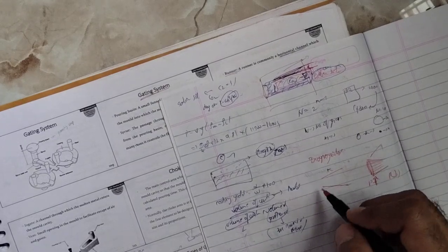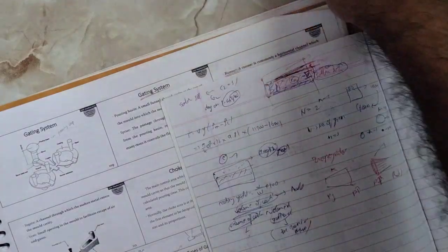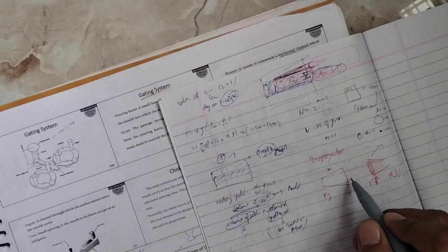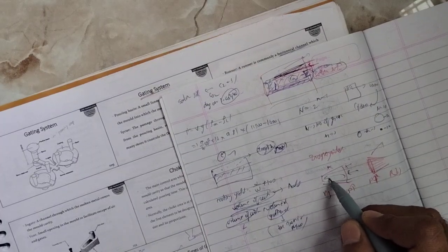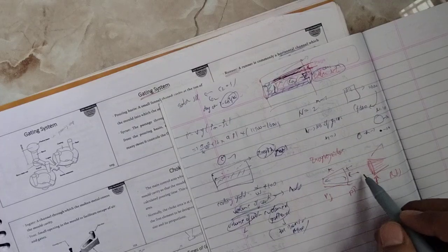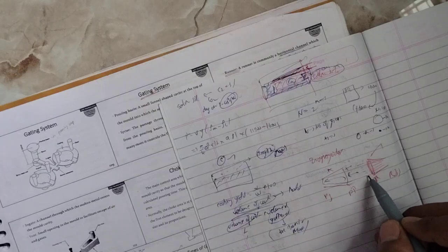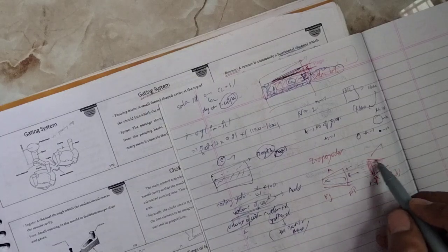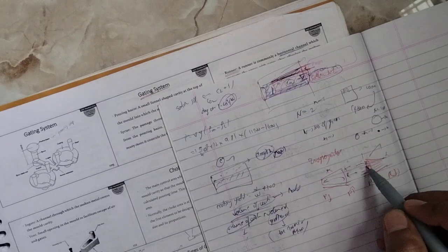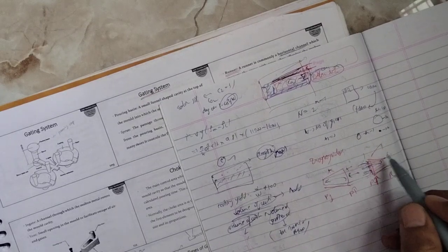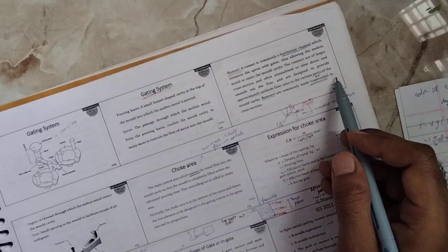Here the pressure will be normal, but here the pressure will be higher, so here the pressure will be lower. It is high to low only. When the material passes here, the pressure will push it like this, so the metal will just go back. Now with the runner placed like this, here the pressure is higher and here it is low, so high to low, and the entire flow will be pushed towards the right side. I think you are getting the point. So runners are commonly made trapezoidal in cross section.